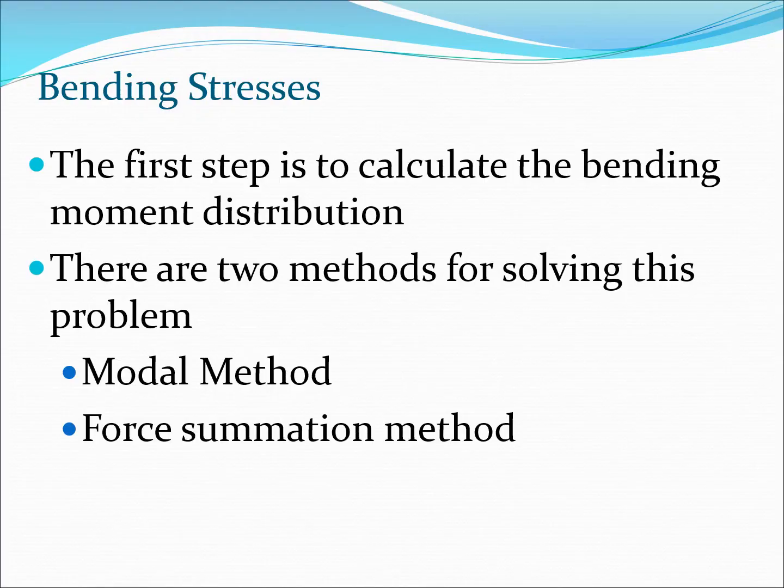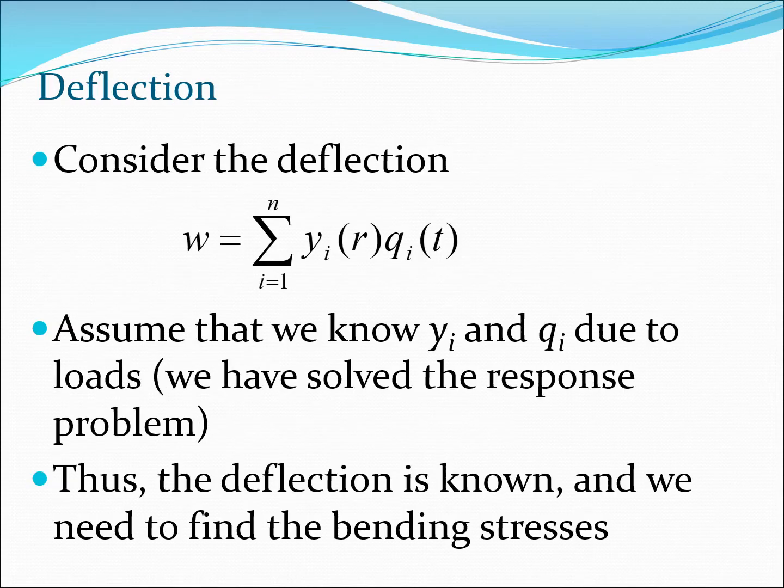Now we know from mechanics of materials that the first step to calculate bending stresses would require us to calculate bending moments, and from this bending moment expression we can actually calculate the bending stresses. Now, there are two methods of calculating bending stresses in helicopter dynamics which are popular. The first one is the modal method and the second one is the force summation method. So, I'm going to discuss both these methods next.